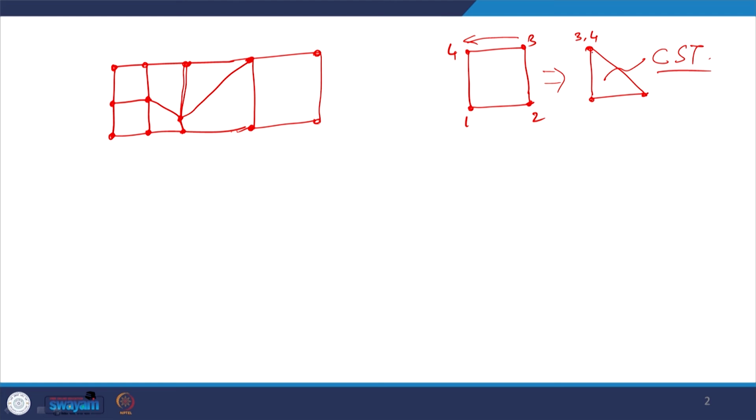Of course, at this particular point, one-to-one mapping has been lost and the Jacobian will be singular at this point. But for a constant strain triangle, we do not need to evaluate the Jacobian at this point, it is constant everywhere. So, we can simply evaluate it at the centroid of the element and get all the computations done, safely away from the point of singularity.